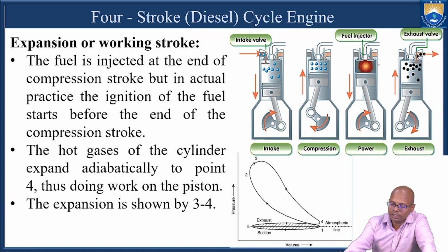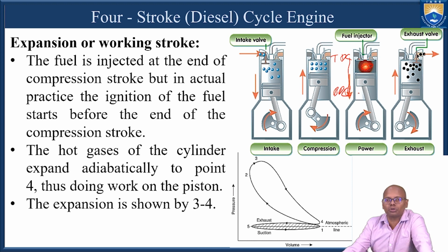In this stroke both the valves remain closed, and the piston, because of the high pressures of the combustion, is pushed from the TDC to the BDC. This is called the expansion stroke or working stroke, during which the power is given to the engine by the working fluid.